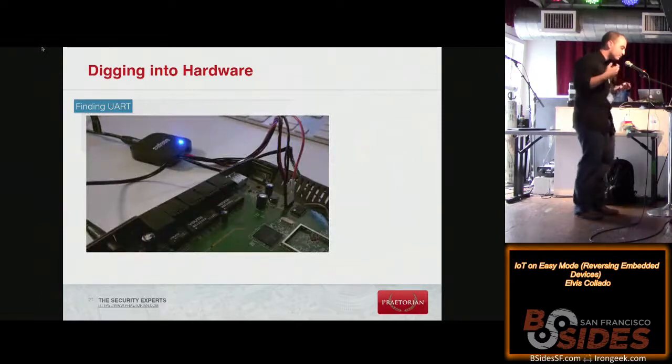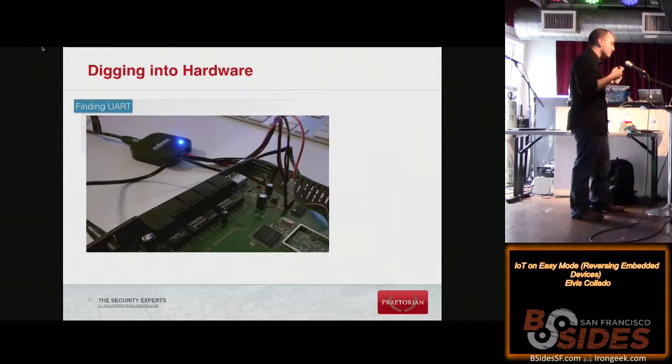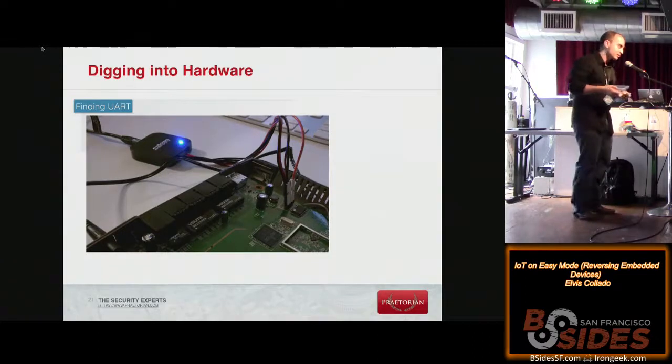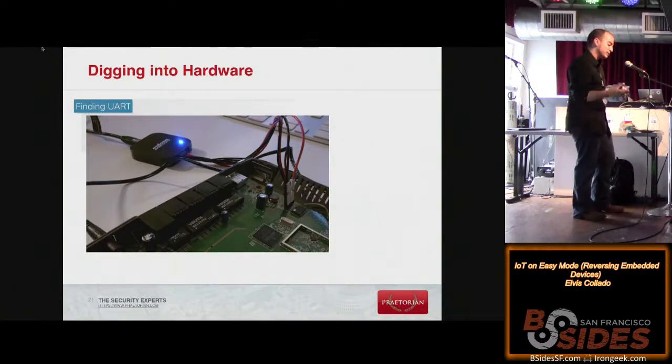But if you don't want to brute force around for the TX, for the transmit on the device, and you want to use a logic analyzer, you can do that too. And I can show you how to calculate the baud rate and all that stuff so you're not brute forcing. So you're not like, I found the TX pin, but I'm getting garbage, so let me try again, attach screen to this device using 9600, 115200, whatever. It gets kind of annoying to brute force these things.